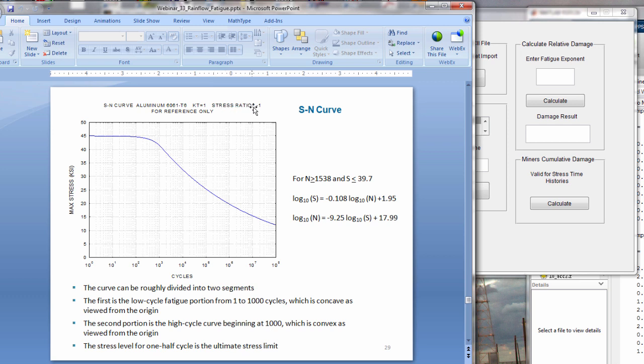Stress ratio equals -1. This means that we have a symmetric stress field, I mean time history, about the zero baseline. But sometimes as you consult the literature, you'll see S-N curves where it's all one-sided on compression or all one-sided on tension, or any permutation in between.